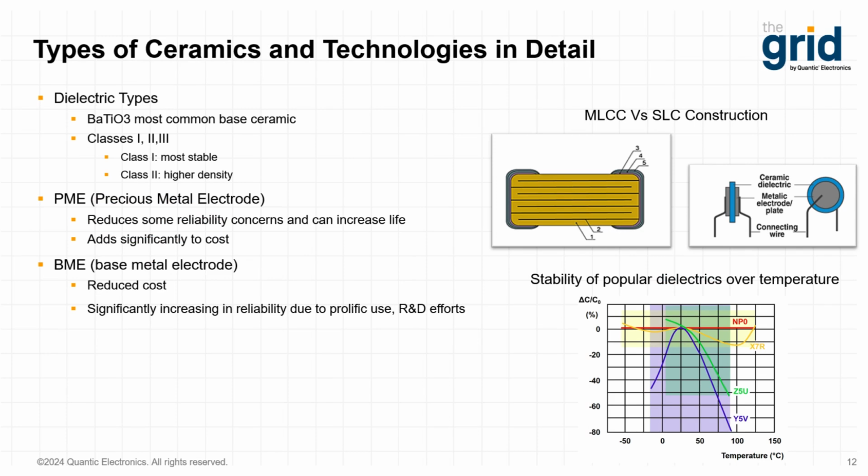Ceramic capacitors, on the other hand, are well known for fast frequency response, low ESR, and temperature withstanding capabilities. Contrasting to the electrolytics that Misha described, these are, of course, of the electrostatic category, and are typically used for lower capacitance applications with higher frequency needs. The two main types of ceramic capacitors used today are single layer ceramic, or SLC, and multi-layer ceramic, or MLC.